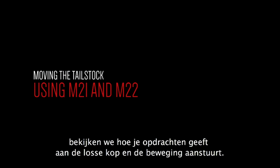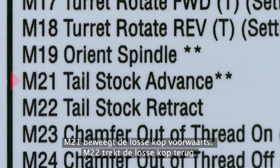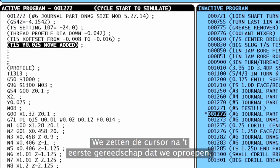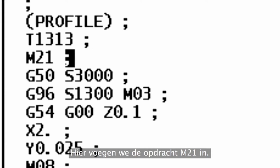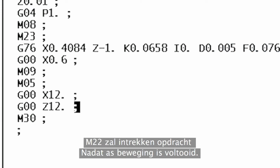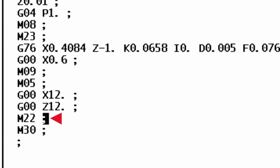Now that our part has a center hole, let's move on to how we command our tailstock and control where it moves. So, how would you tell the tailstock to move forward and retract? M21 is the tailstock advance command, and M22 is the tailstock retract command. Let's add these commands to our program. We cursor down to right after the first tool is called, and this is where we insert the M21 command. And at the program's end, this is where we'll insert the M22 retract command after axis motion is complete.